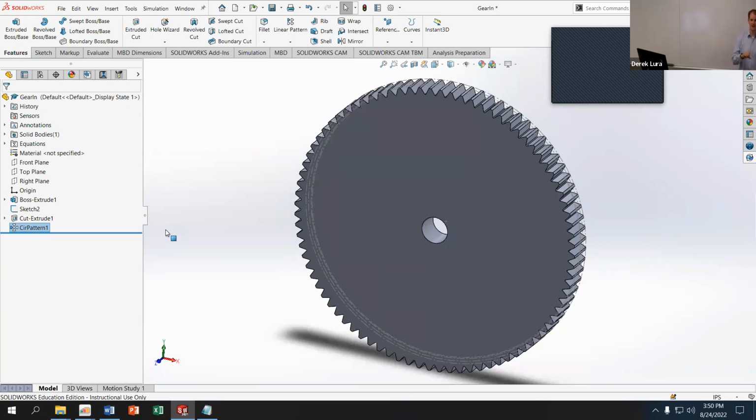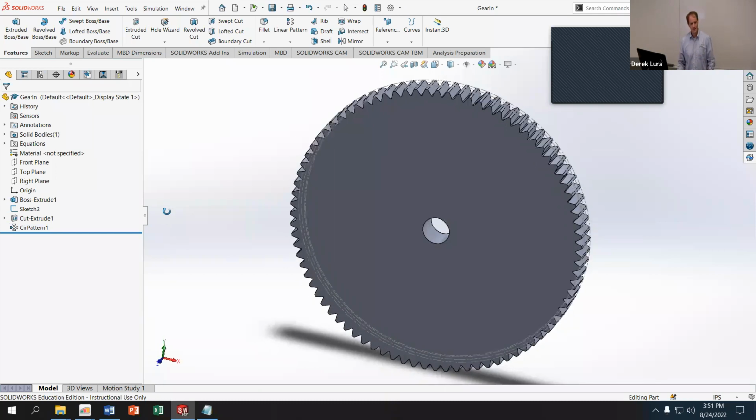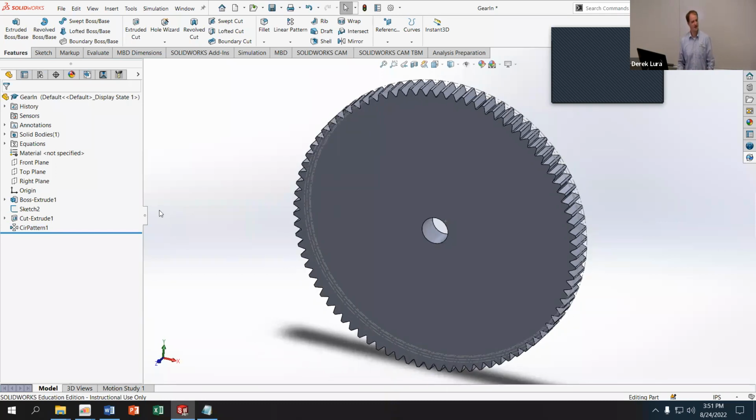And if you have to err on the side of clearance versus interference, err on the side of clearance, right? Does that make sense? If you're designing for something, if it's going to be varying, you probably want your variance to result in a clearance and not an interference, especially if you want things to move, right? Like I want these things to mesh and then to move relative to each other. If the teeth interfere with each other, that's never going to work, right? They have to have some clearance around them. Anyone have questions on that? Did that work out for everybody?